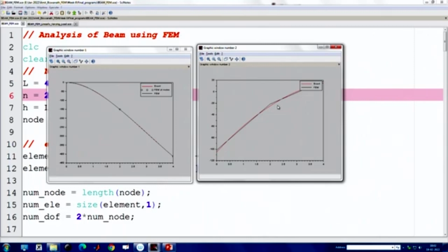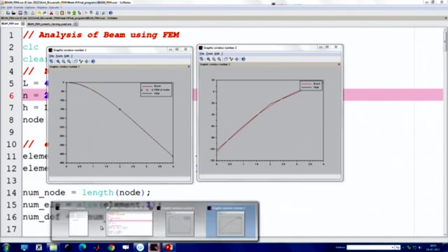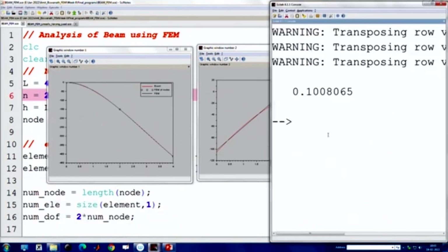The finite element solution can have a different expression, a different curve from the one obtained from the exact solution, but from the finite element solution with cubic B-spline polynomial shape function, the bending moment between 2 points is linear. Now, this is relatively better. What is the error? Initially it was 1.6% and now it is 0.1%.